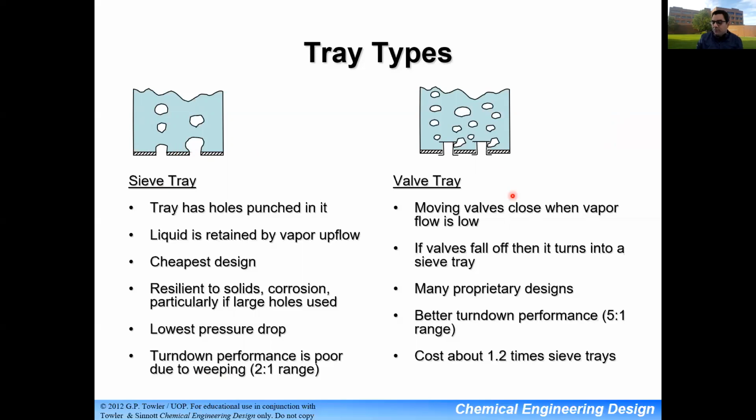The second type of tray is called a valve tray. If you look at it here, I have valves, and with this design, the valves basically push the gas to leave from the sides, instead of just bubbling straight up, they bubble from the sides.